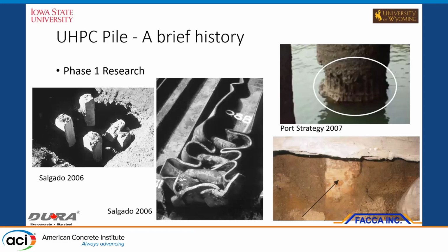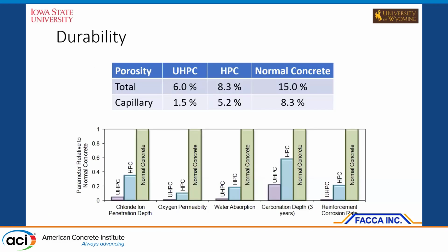I got into UHPC pile design back in the 2006-07 timeframe because of what we typically experience with regular piles, whether steel or concrete. Steel and concrete piles do go through damage during driving. We wanted to see if UHPC is a better solution. Obviously, durability is the other component. That, along with the unique properties that you have probably learned a lot about over the years, attracted me to look at UHPC piles as an option for the DOTs.